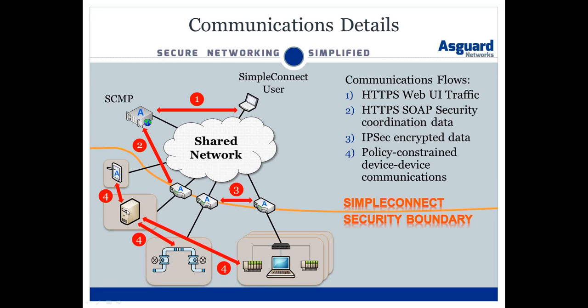So we can add policies that say limit this server to communicating with this PLC using, say, Modbus TCP, and communicating with this water flow meter using, say, OPC, and communicating with this tablet, say, using HTTP, right? And so we can prevent this flow meter from communicating with this PLC or this server from communicating with this other PLC, right? We're not going to be doing anything about the communications within this automation cell. This typically will be a very high-speed, real-time control network. But for the purposes of doing SCADA, we want to be able to extract data out of there. We want to occasionally allow remote access into this environment to view or maintain the systems within it. And we want to make all these private networks very easy to manage.